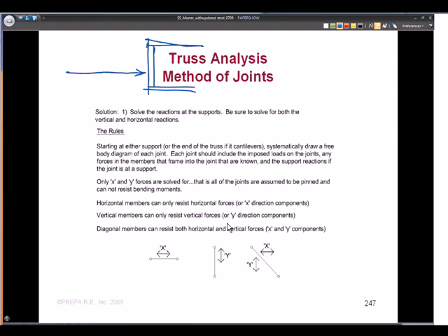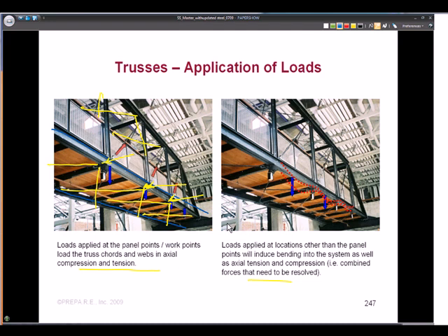Right, since the cross bracing is rods, they will always be in tension. That's exactly right. So that's why they've got them going both directions. In one instance, when you push on this, only one of the rods goes into tension when it pushes through and pulls on these guys. But if the seismic force is coming the other way or the vibration due to the people, then the other ones engage and go into tension. So that's why they're crossed, so that all their bases are covered, to make sure that they're tension only members. That's exactly right.